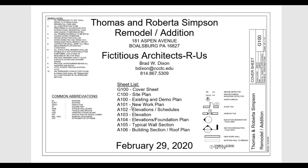So to go to our set of drawings, the first thing that I want to point out is on this cover sheet, a lot of times what you're going to find is a sheet list. That sheet list is going to give you a brief description of what sheets are included in the set of drawings, what the sheet title is, like this would be cover sheet, and what the sheet number is. Just to give you an example, over here in the title block, we're going to have the sheet number. In this case, this is G100.